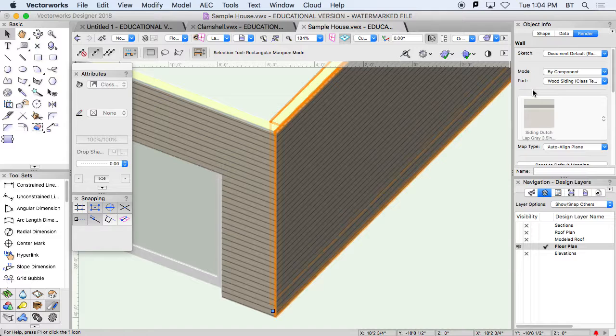So grid lines are great for drawing and guides and angles and all that. But when we start creating shapes, even with our double line polygon tool, there is the option to create lines, and I always create polygons, because most often if I'm wanting to create a separation, that separation is representing an object, so I'm going to want to keep it as an object together. If we just create double lines, then they're separate, and I can't manipulate them together, right?